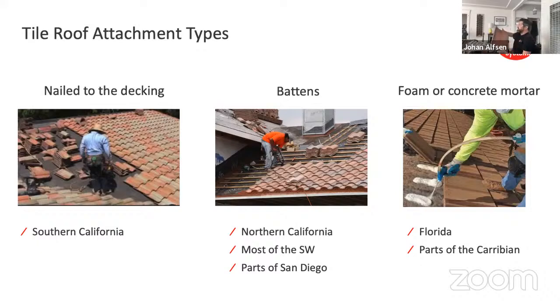The S tile you can see is much bigger, much heavier, and it does still have a lug there. It's a lot easier to grind that away and have a tile hook come out if that's what you want to do. But they have that S shape. They still have that cap and pan interlock. They're a lot heavier. They obviously still have the nails in there.